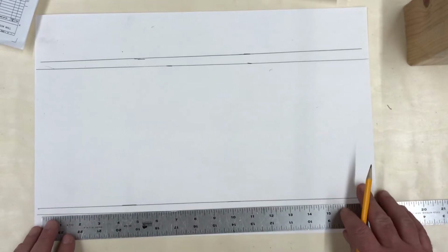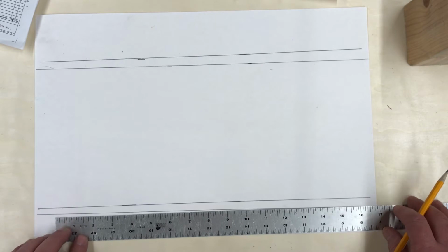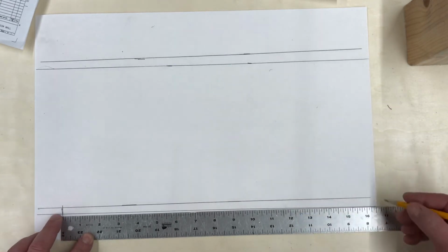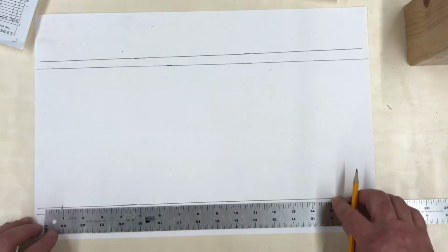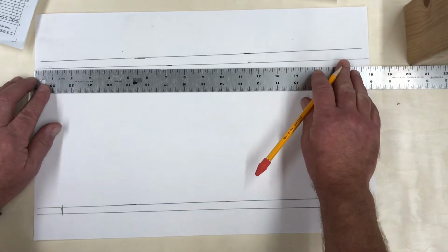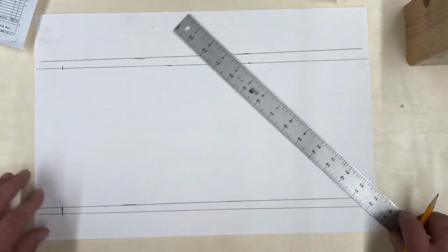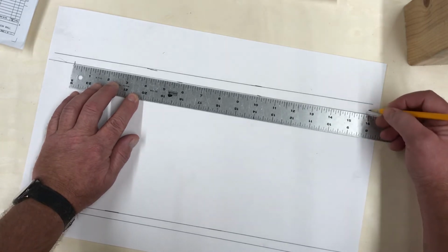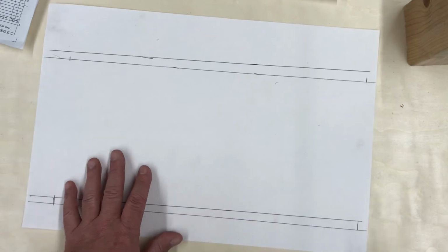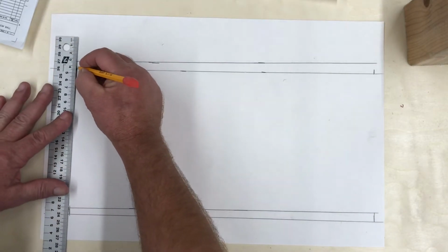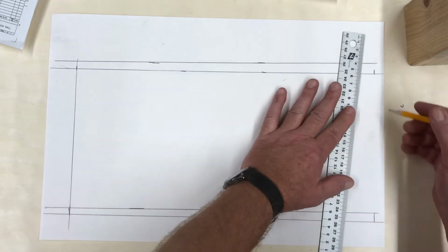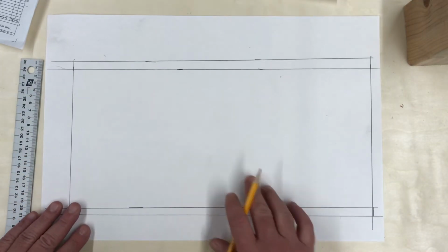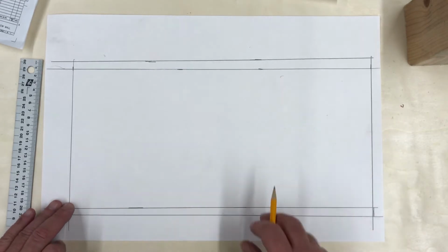So I come up here with a ruler, we're going to start right here, and we're going to measure 16 inches over. Now, what I want to do here is go 1.5, 1.5 to do that, so I can measure 16 inches over on this wall. And here's 16. We take a shorter ruler or a stick, whatever we have, and we're going to draw this in, and draw this in. This now sets the parameters of where our wall sits. So there's our top plate, bottom plate, and there we go.